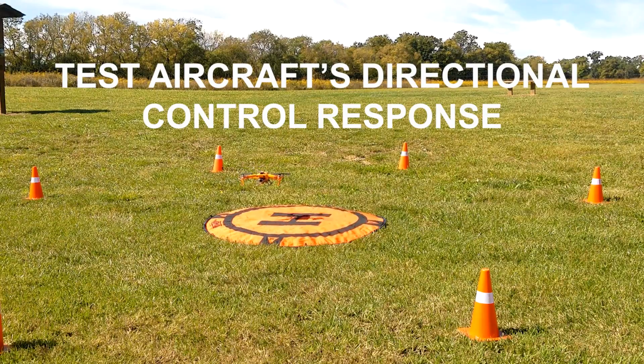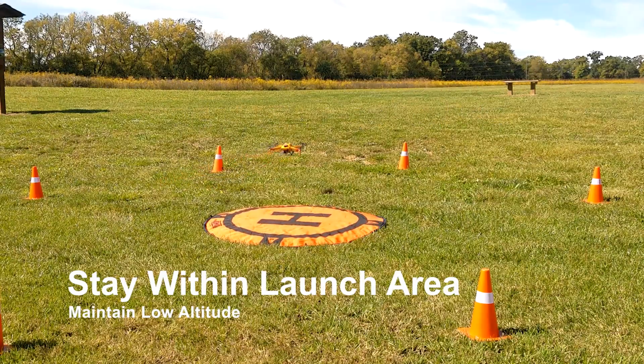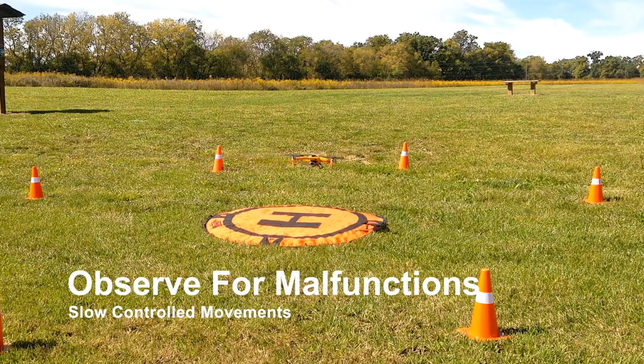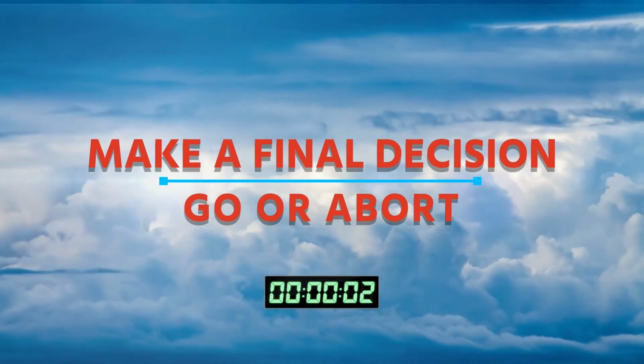Then you need to test the aircraft's directional response to your flight controller's commands. This is accomplished with slow, smooth movements, moving the drone forward and then to each side, then bringing it back to center and reestablishing your hover. How your drone responds to those commands will tell you a lot about the health of your drone.